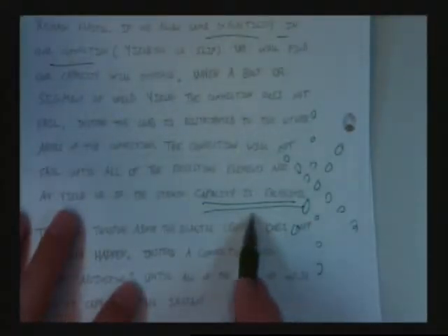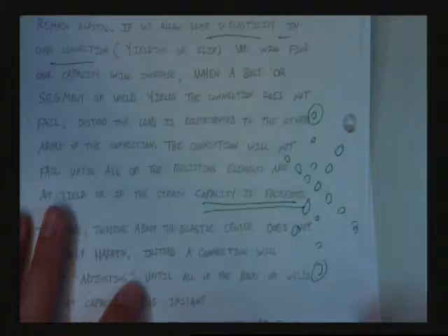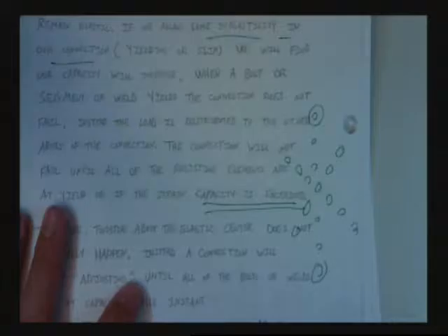But what one would do is this: the idea that the individual strain capacity is not exceeded now becomes very important for this bolt and this bolt. If we assume all of these are going to be yielding and at their limit state, this bolt and this bolt may no longer be, and that may be a very bad assumption. One would have to test that. How do I know what kind of strain capacities I'm going to be able to get out of these bolts? Good luck. You need to do some tests. You need to ask the manufacturer what kind of strain capacities they think they can get out.